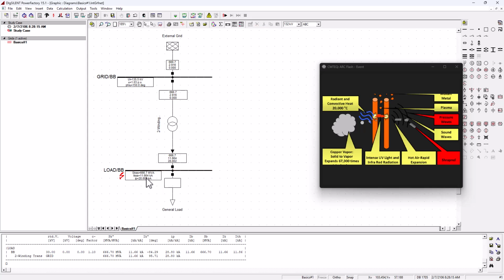Now even though this bus bar has a lower short circuit current compared to the 43 here, because of the distances between the conductors that are going to be energized to cause an arc, you might get a higher incident energy compared to this point here, which means your PPE level might be higher than here. I'm just saying, but we're going to discover that in a moment. So make sure you apply the distances correctly, as we're going to see now.